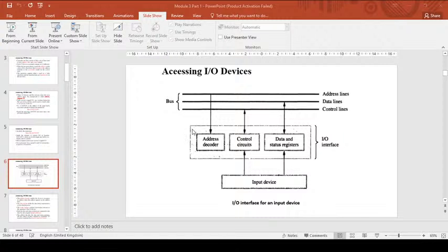Okay, and then increment the location. Line plus 1, to the next location. Transfer the character from the register R1 to the memory location present in R0, that is line, and then increment the memory location. That is what is done here.